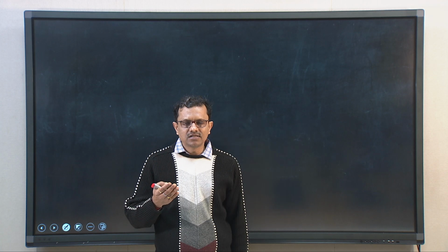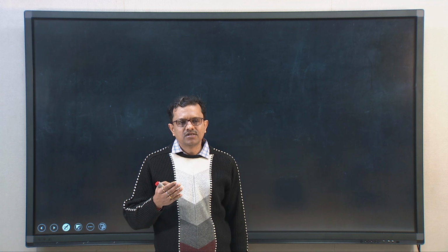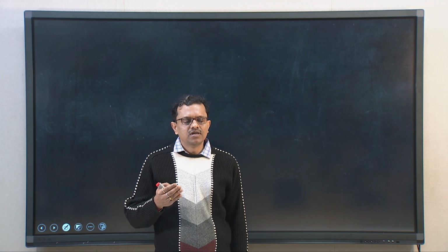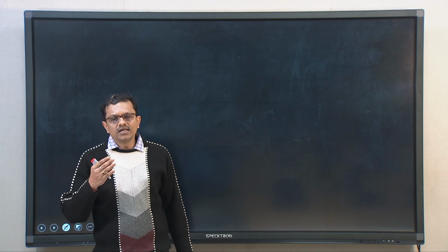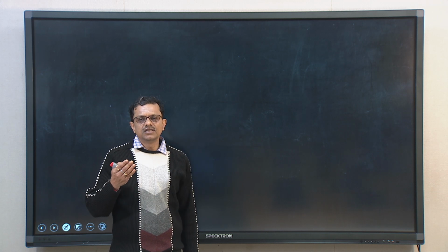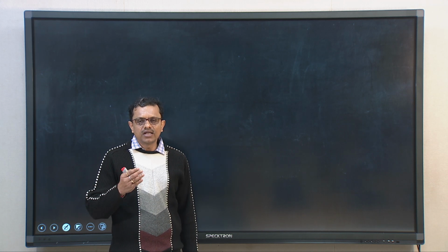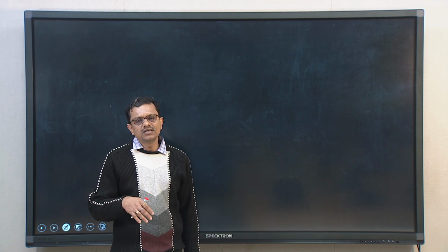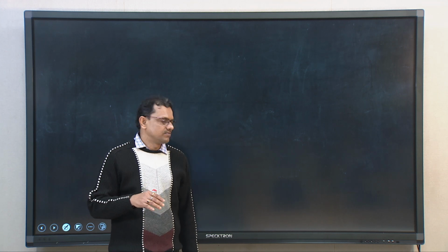So, let me write here that in a digital electronic circuit, the control input to the transistor switch must be capable of running the transistor either in off mode or in the saturation mode without allowing the transistor to run in the active or linear regime. Okay. So, that is very important.